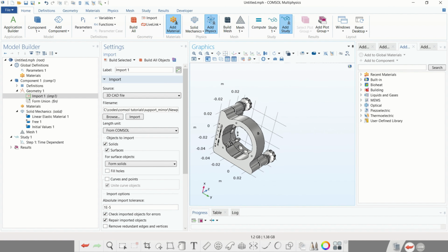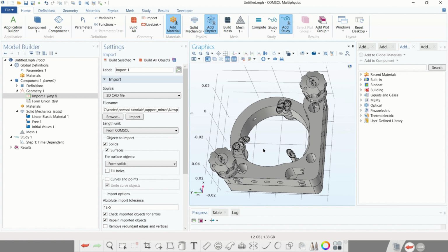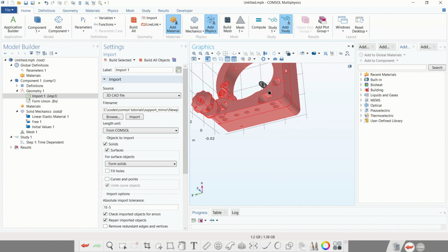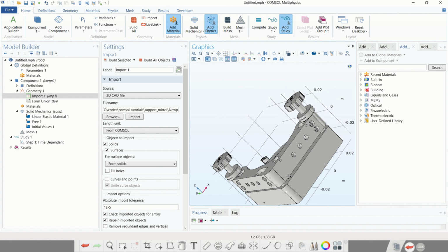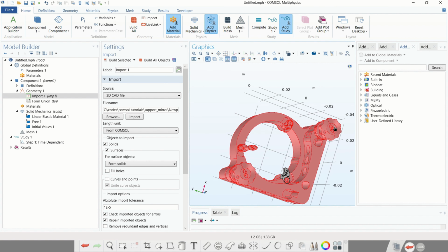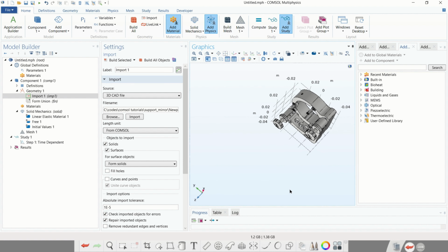As you can see, you have a logo here, you have other parts, and immediately you see the first problem. The first problem is that you have only two parts. However, you would like to have a complete disassembled structure such that you can manipulate certain objects, such that you can fill in the holes, simplify the geometry, and reduce these knobs since we don't need them. They're not essential for our simulation.